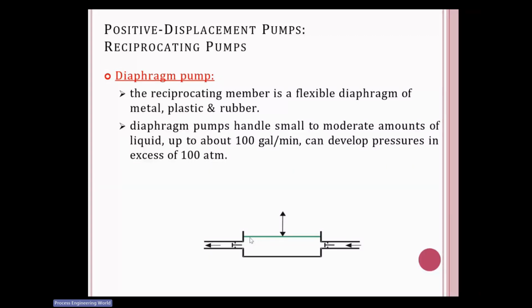What I want you to understand is that there are certain limitations of diaphragm pumps. Usually the chemicals which are used inside chemical industries are highly flammable. If they make contact with air or oxygen, they can generate flames. Okay, it can burst. So in that case, we usually avoid AODD pumps.